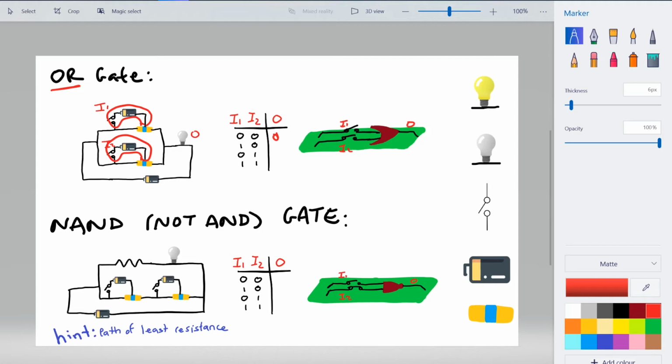Okay, say now we turn on input 1, so close the switch on input 1. Now electricity coming from our output battery, once it gets to the junction, is able to get through the first transistor, so continues flowing down and then goes through the output bit, and so we have a completed circuit, and so our output is 1. Flipping the switches now in our third case with only input 2 on, again, electricity is going to be able to flow through now the second transistor, and the output bit turns on as well.